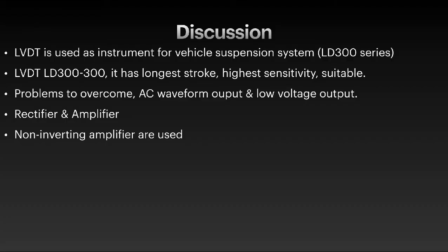To sum everything up, as for our discussion, we use LVDT as our instrument for our vehicle suspension system. Precisely, we use LVDT LD300 series because it has the longest linear stroke of the LD300 series. It has the highest sensitivity and is also the most suitable for the car suspension system.